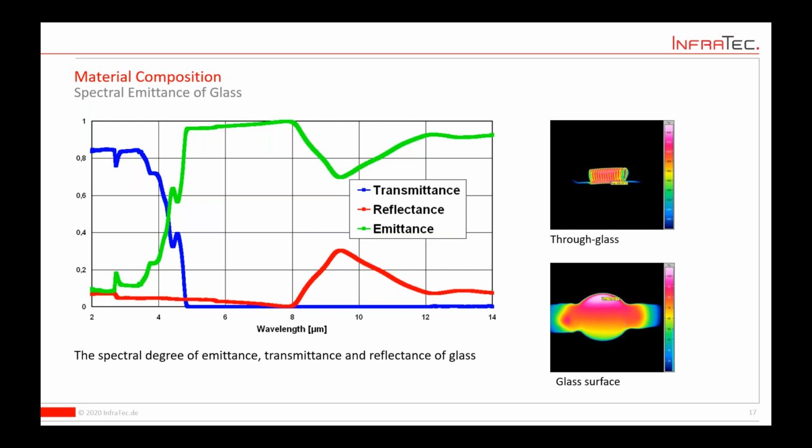So that makes it highly likely to measure on the glass surface. But on the other hand, if you do not want to measure on the glass surface, but look through the glass, you are thinking about a wavelength more between 2 and 3 micrometers. And by simply thinking about the wavelengths of these spectra, you can choose your IR camera according to your tasks.